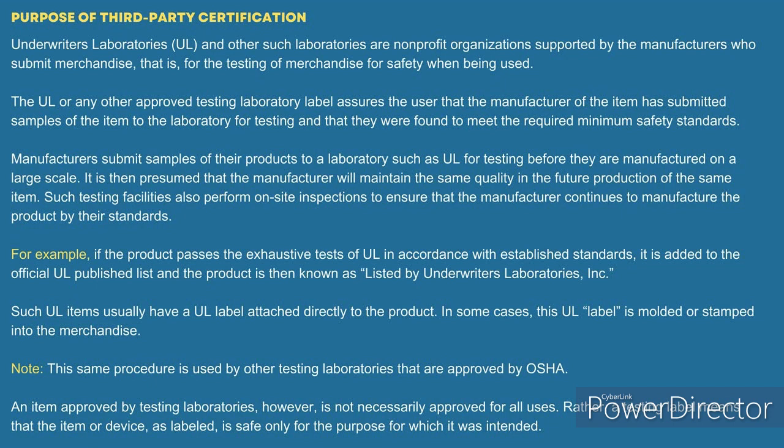So I think 250.114, I think we talked about this before. I think it's when you are able to not use an equipment ground. Like I believe 250.114 is when you use a GFCI in lieu of one.